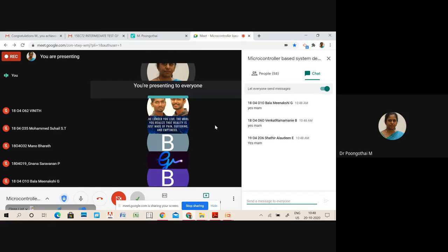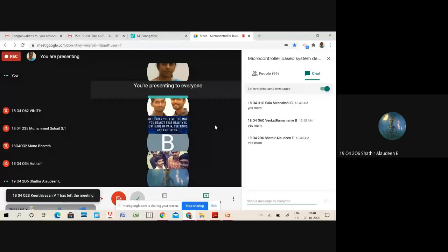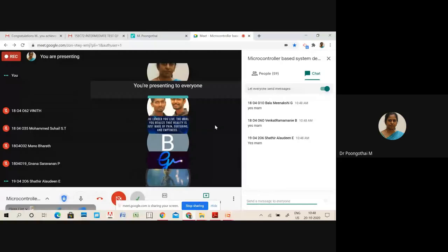Alauddin, can you explain that reception problem? First, explain the steps involved. First, we need to initialize the timer mode register, timer 1. And the baud rate given is 4800, so we have to load the higher order timer register with FA.